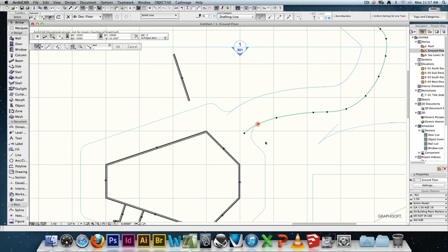So you've got to understand the logic that's happening when you're offsetting an edge: you're making that radius smaller and smaller. Eventually, the radius is gone. If you can't go any further, that's cool. Just go as small as you can, clean up that corner so that it's now just a straight edge, and then you can keep going, because then it's just offsetting the edges. That's all it's doing.